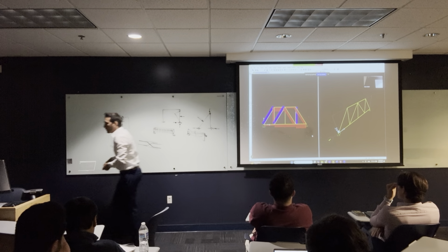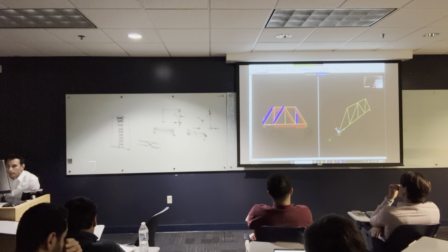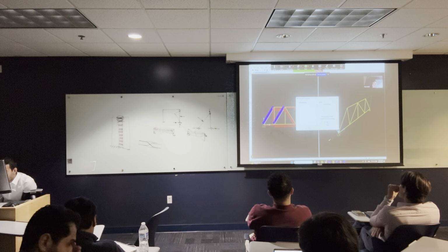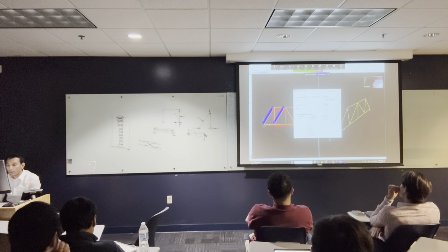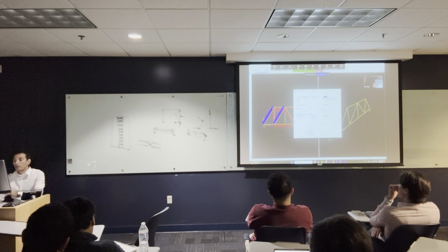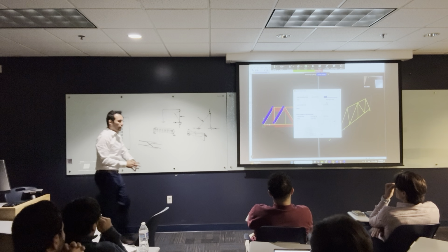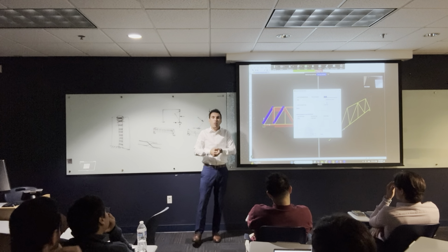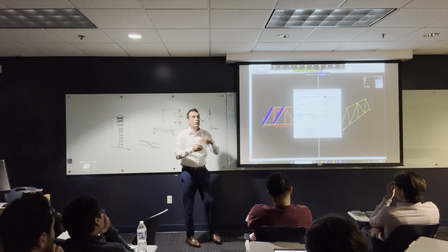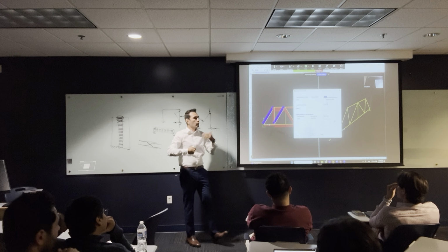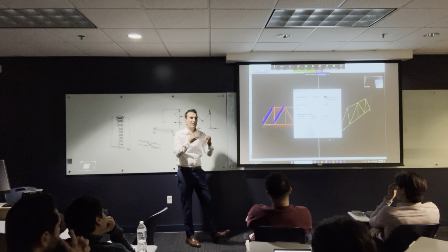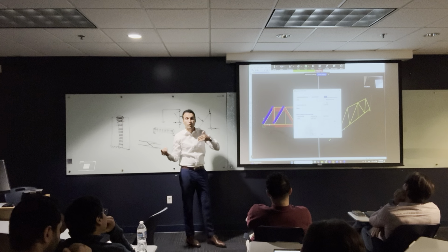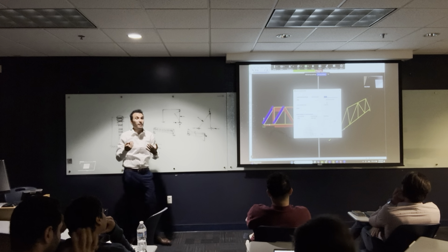So how can we do these combinations? I'm going to go to define load combinations, and I'm going to add new load combo. So I'm going to make a comp 1. The thing is, when we design a structure, we don't design them for load patterns separately, because live load and dead load and seismic, they all come together. Dead load and live load mostly are together. But we do load cases, like one with seismic without wind, one with wind without seismic, one with wind and seismic, but we reduce their factors. One with rain, not with snow, and one with roof live load without rain.